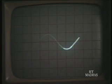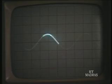So, this is AM detection, this is called synchronous AM detection using PLL, this is frequency selective. So, this also can be adopted, strictly speaking, for radio receivers, but at the time of radio receiver design, this idea, even though it was proposed, was rejected because the PLL was very costly in those days, and what was selected was the superheterodyne receiver with a simple diode as the detector at the receiving end. Okay. Thank you.